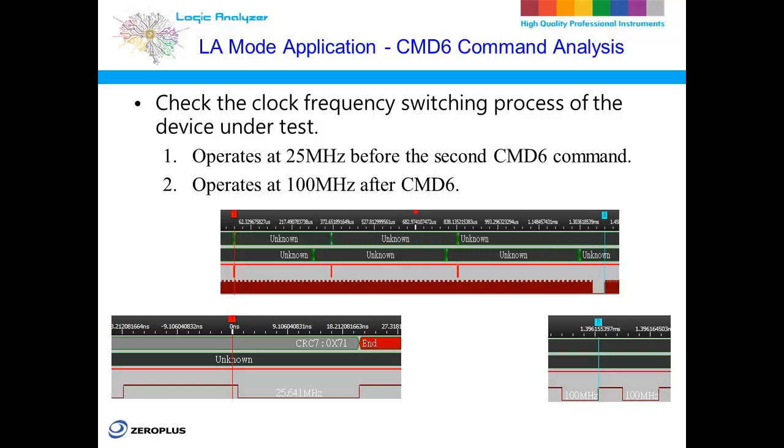This frequency is the standard operational clock for SD cards or eMMC in normal mode, and all data transfers and signal processing occur at this lower frequency. Using B2, we can observe the clock's stability and signal shape at this stage, which helps ensure stable device performance early in operation. At this stage, the signal is stable with minimal fluctuation.